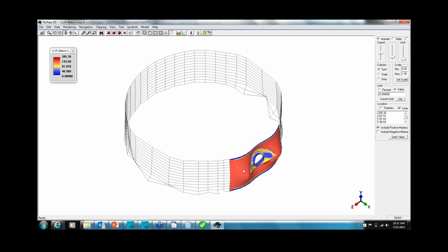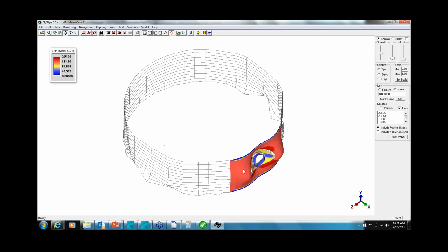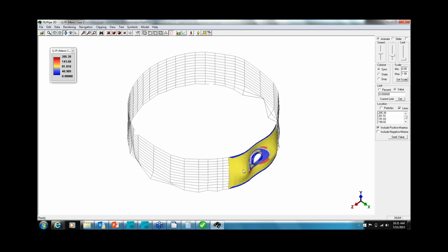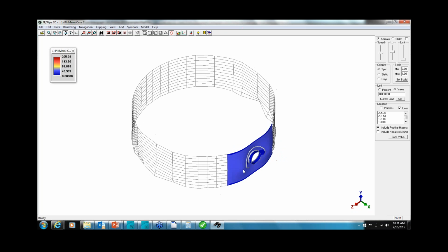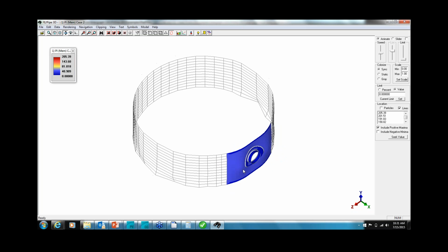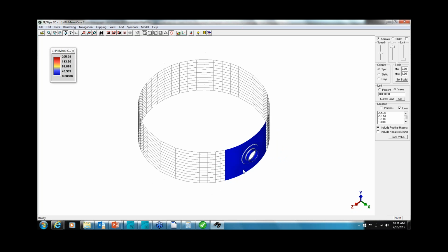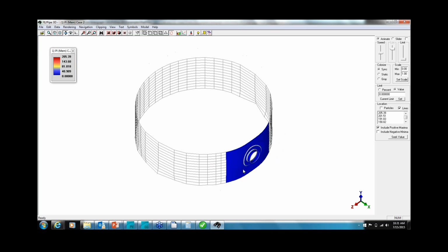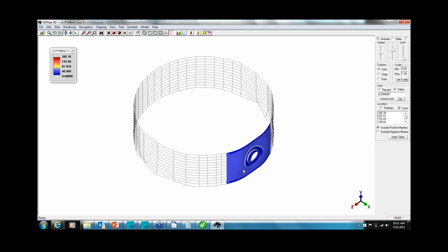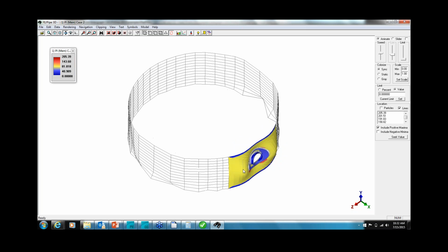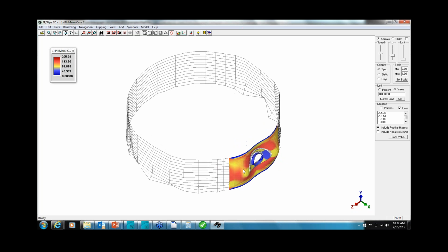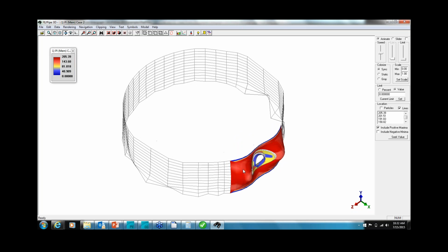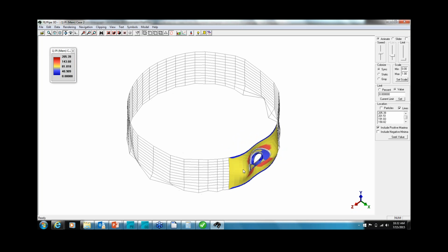I need a normal meshing on the vessel area, whereas at the nozzle and shell junction, a very fine meshing is required. Here, Nozzle Pro is template driven, so it takes care of all these requirements automatically for you. All that we have done, in the CodeCalc area, is change WRC 107 to FE analysis, and we are getting the results for the same applied load.